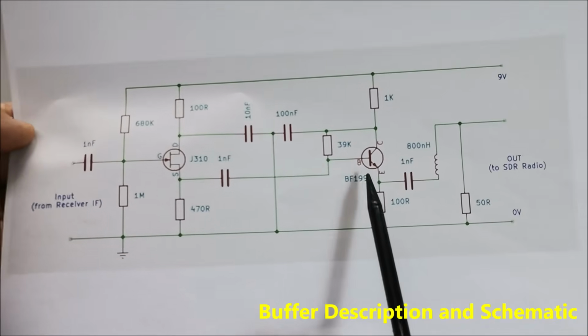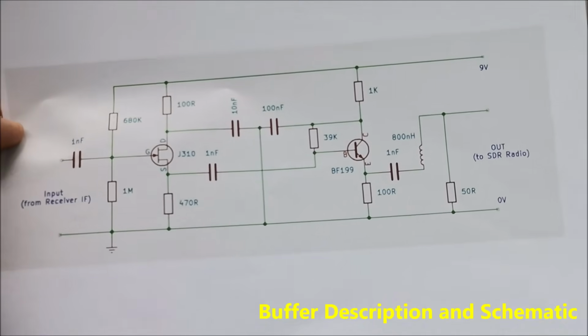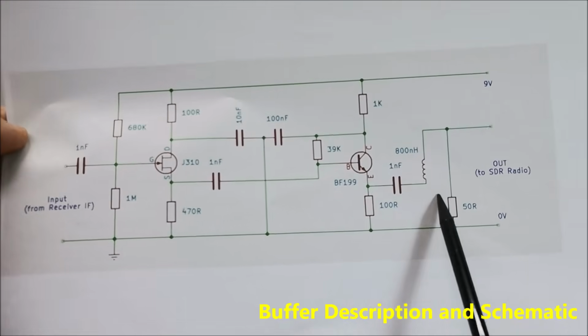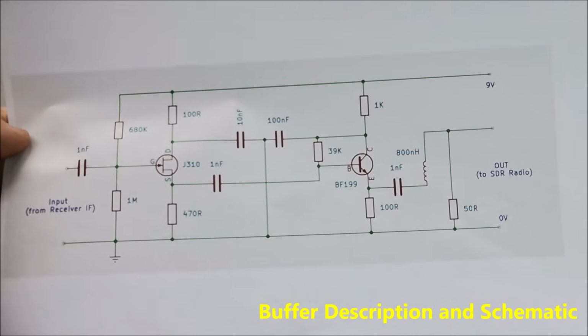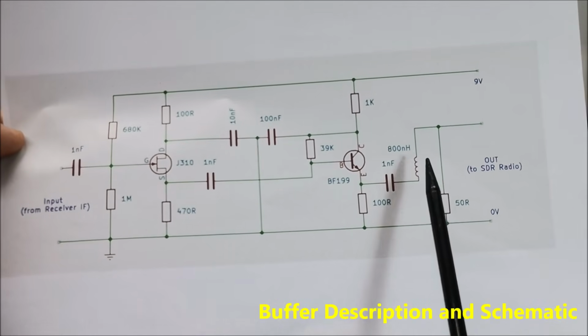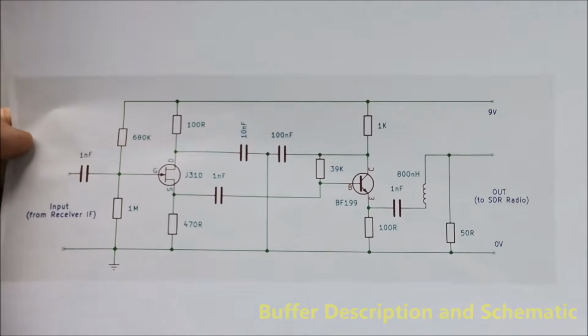Then follows a BJT transistor as an emitter follower to provide impedance transformation for the following filter stage. And finally, I added a very simple 10 MHz 3 dB low-pass filter consisting of a single inductor and resistor.